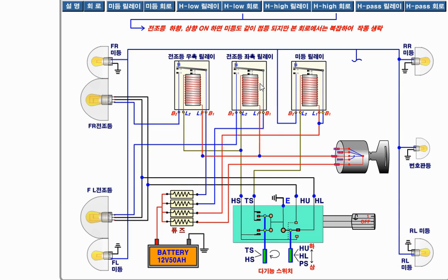So that will make direct current be drawn from this battery, and then current will flow from this fuse towards this headlight, and this fuse towards this headlight. So that's how the current flows in these headlights. Now for the low beam, this small filament will be illuminated.